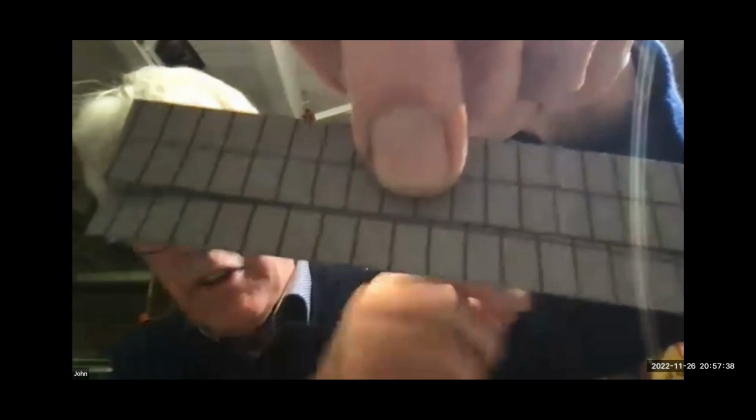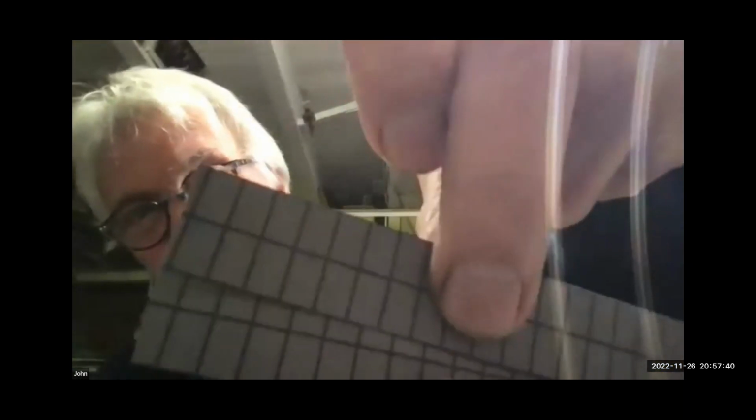just literally place them on top of that one, on top of that, and keep going ad infinitum up the wall. Lift it up a bit, John. That's it, we can see it now. So you're just doing one on top of the other. The idea is if you do them halfway, I mean, real slate should actually do 2/3, but that takes more slates. So just wander up the roof, measure straight lines on your roof and line them up.